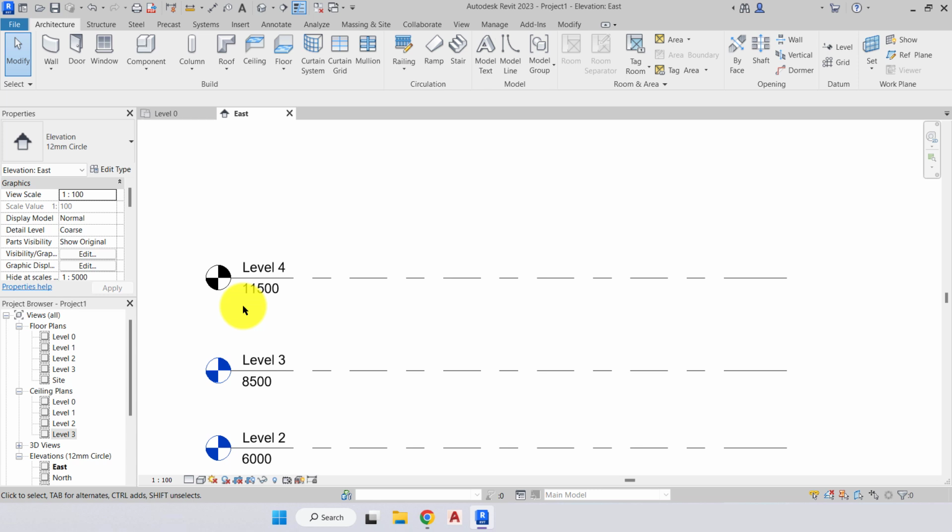When we're creating our components, we want to always constrain them to something so that they can be locked in position. And if we ever want to make adjustments to heights, if it's attached to a level, it means that we can adjust all of those components at once, saving us a lot of time having to go back over and doing that manually. An example of that would be a roof ridge. If we wanted a particular level for our roof ridge, we can set that. We can also use it for eaves details when we're creating eaves.